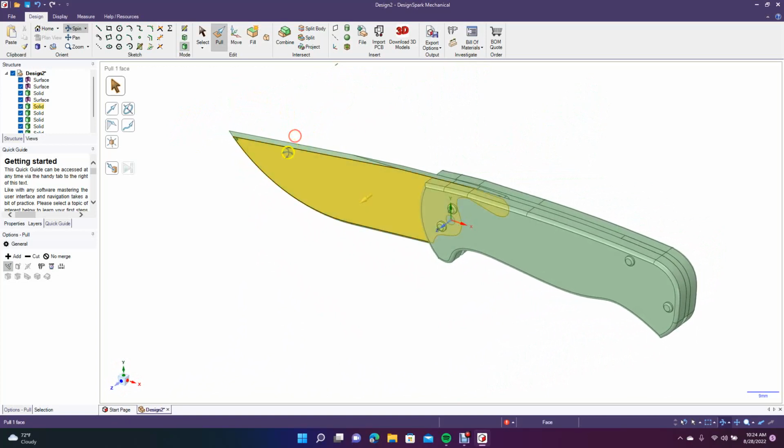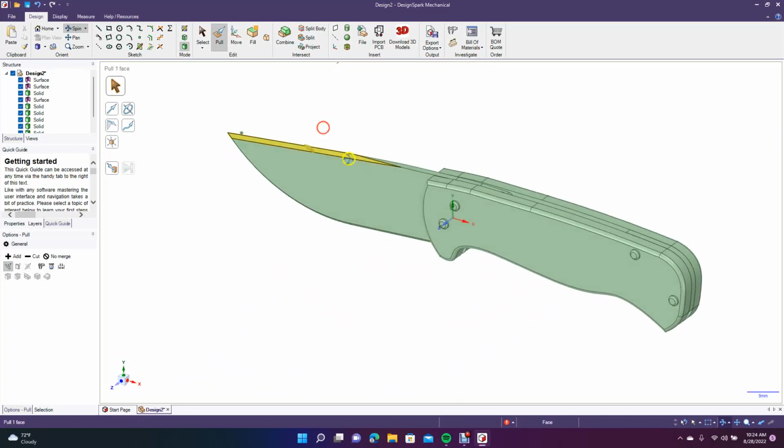Okay, so just an overview on this, what we needed to do when we created this is we created this knife blade. Then we created one of these scales with the holes here, and then we created this little block in the back to keep the blade from going anywhere. Then we kind of moved stuff apart from each other, and then we extruded this left scale out. We extruded that 4 millimeters. And then we extruded the blade out 2, and then we copied this one and we created another one over here, but we created it 4 plus 2, so 6 millimeter move.